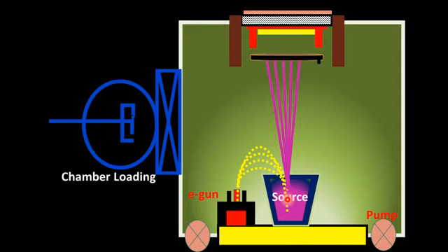If we want to deposit a silicon based thin film via molecular beam epitaxy, the melting temperature of silicon is too high, around 1400 degrees centigrade, so there can be a very high temperature inside. Since MBE is a low temperature based technique, electron beam evaporation is more common to evaporate materials which have a high melting point, like silicon.